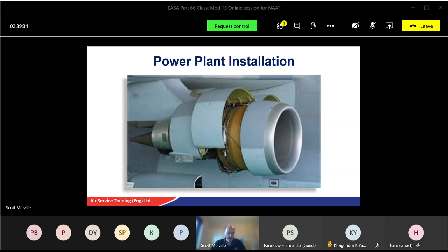The oil temperature switch is set at what temperature to close the APU down? At what temperature will the oil temperature switch activate? 124 degrees Celsius. Yeah, it's too hot. We're cooking oil. Unless we make it a nice curry, we don't want it that hot. If the temperature exceeds 124 degrees Celsius, it will shut down. Thank you very much. Good.